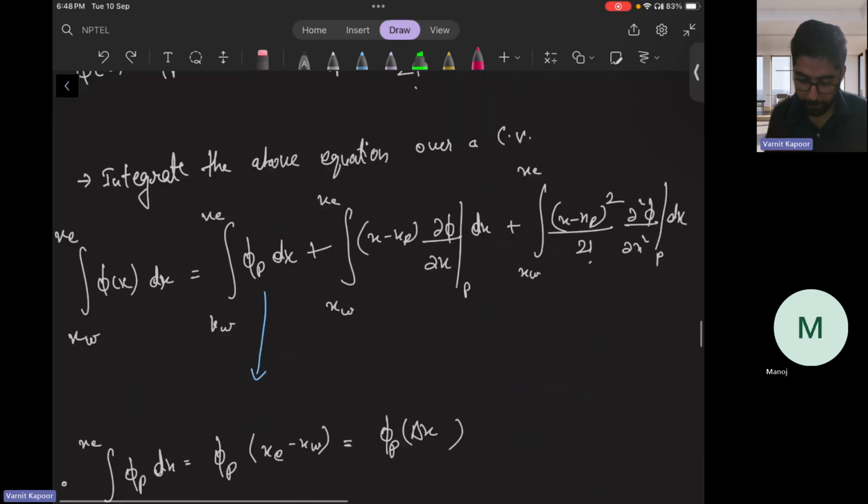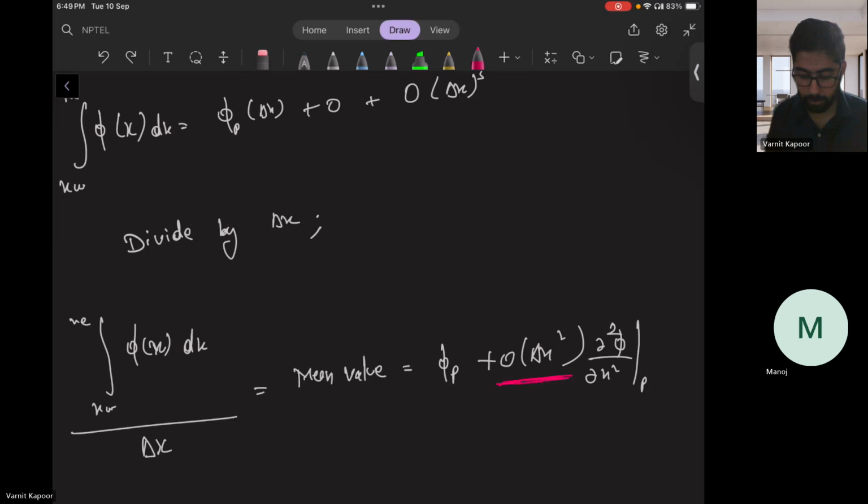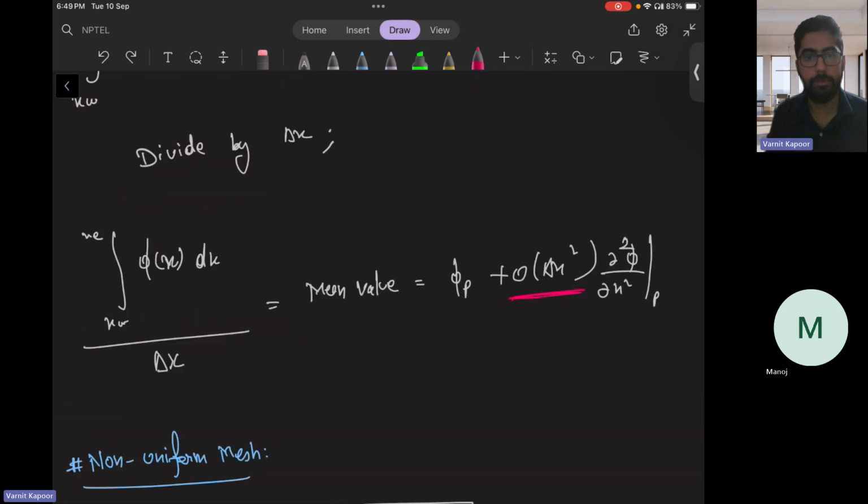Similarly, above, when you were solving for phi, how much order accurate was it? You see, it was again second order. Any doubts still here? Just observe once. Okay, both of them are second order accurate for uniform as well as non-uniform grids in spatial. The steady diffusion equation is also second order accurate for uniform grids. For non-uniform grids, the gradient calculation is first order.